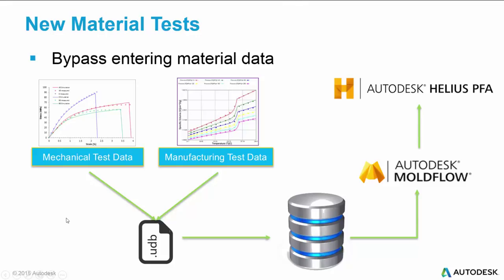And you get to use that data at will. Well, we've done the same thing for mechanical testing now. So if you ask Autodesk to test your material mechanically as well, which means we'll get those 3 stress strain curves for you, we will go figure out what parameters need to be in the UDB file for you by running some dog bone specimens on the FEA side. We will update the UDB file and pass it back to you along with the mechanical test data. Once we've done that, you can put it in your Moldflow database and you can go run your Moldflow problems.